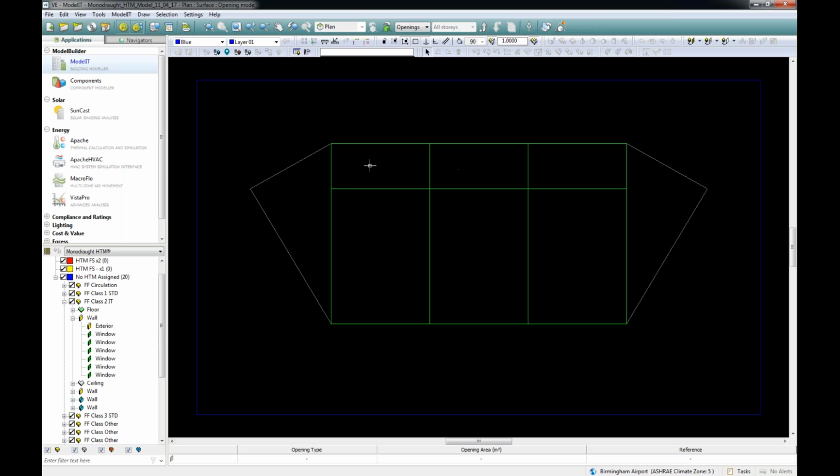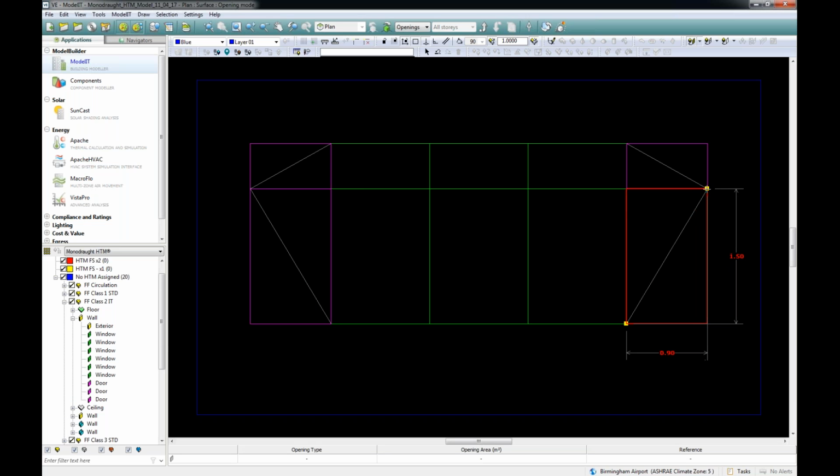So I'm going to drop down to surface mode, and put in some construction lines previously. I'm just going to add the doors in here. So on here, we're going to do the 900 by 500 for the HTM Systems, like so. And then the louver panels are going to go below, which would effectively replace a glazed window panel.